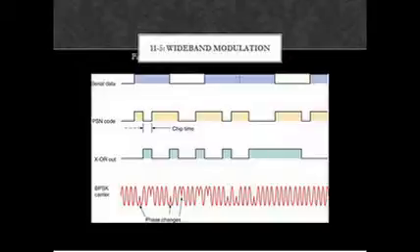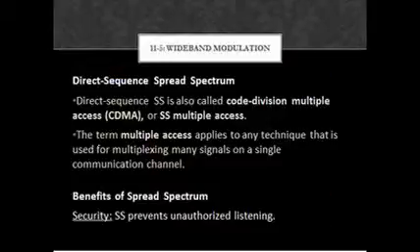At the transmitter or modulator, the serial data is modulated. Then a serial to parallel conversion is performed. The inverse fast Fourier transform is then implemented. This process produces all the orthogonal subcarriers. The DA converter converts the OFDM signal to analog form and transmits it over the communication medium.